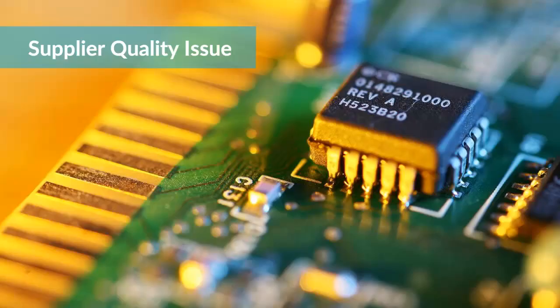Now, the cause could be a number of things, but let's assume this board was just delivered from an outside supplier. As a result, the cause would be supplier workmanship. This information would all be recorded within the nonconformance document. The circuit board would then be taken out of the inspection process and set aside until the disposition, or what to do with it, has been determined.